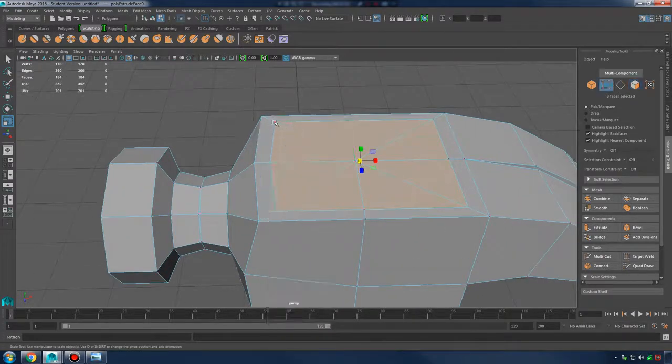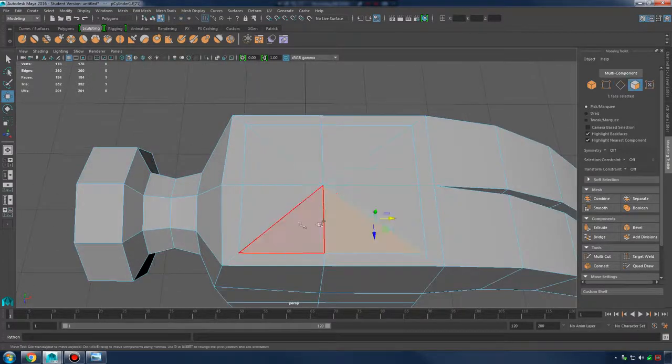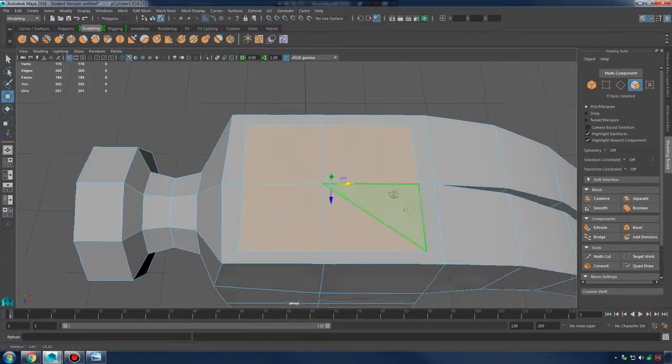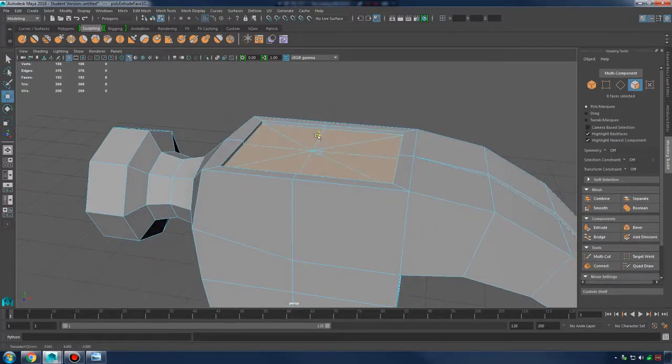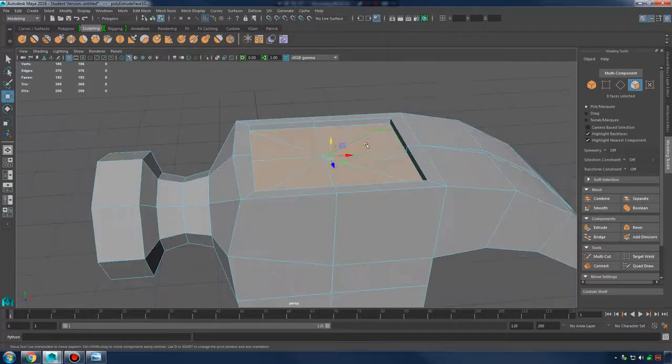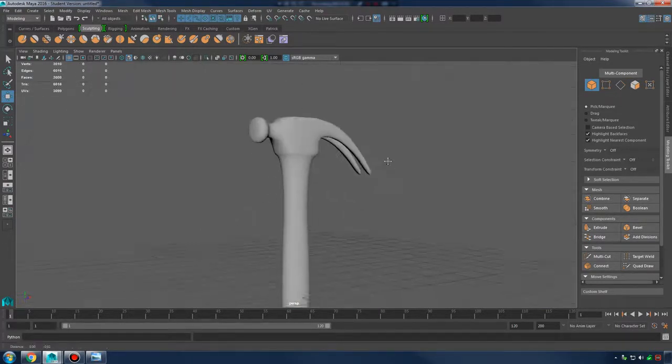And you can see that I'm not quite getting the box shape that I want, and that's just a simple matter of snapping this vertex right here. Now I have my rectangular shape back, and since there's not too many faces, I'll just select them one by one, and I'm going to just extrude them down. Kind of create a little divot there. Alright.